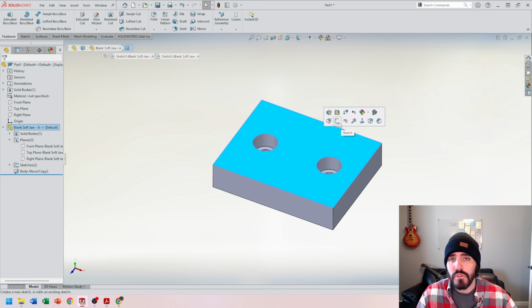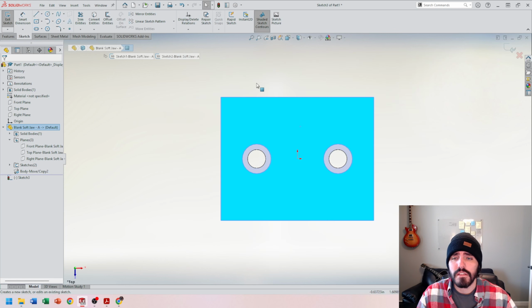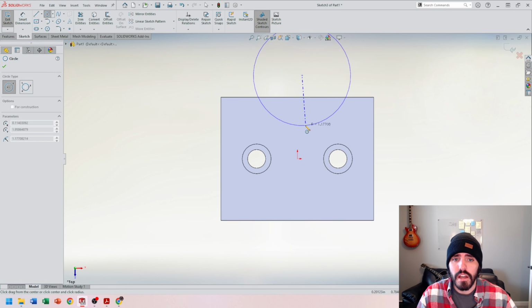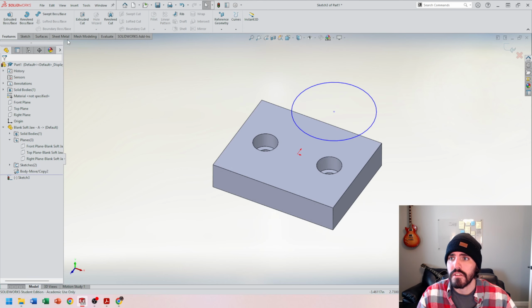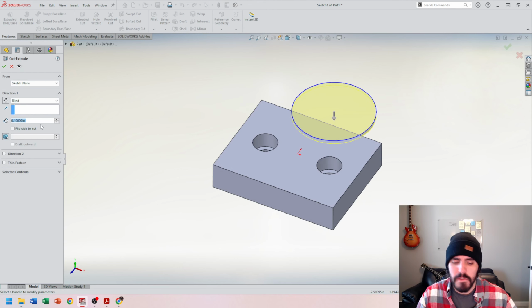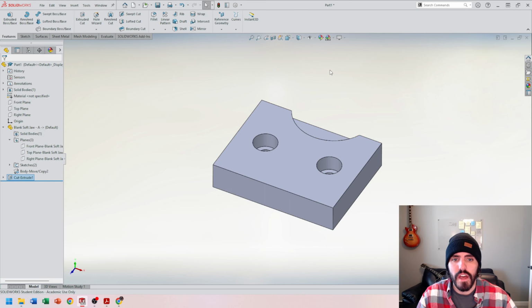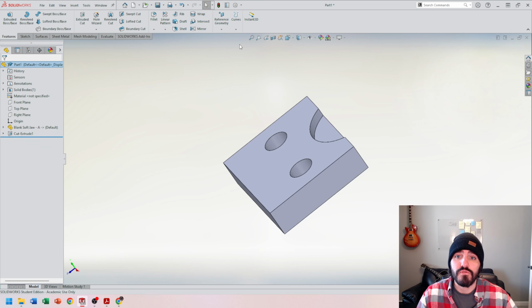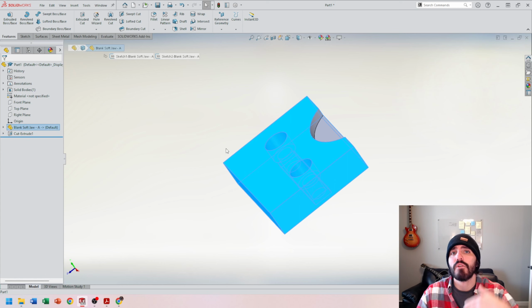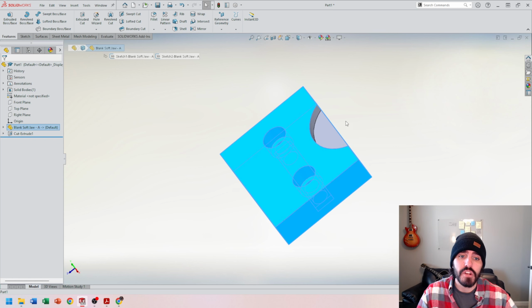But all I did with all those different soft jaws is I went in and applied geometry and then I did a cut. Or sorry, that's an extrusion. I'll do an extruded cut. I'll cut that down that distance. So that's all I was doing. All I was making was a new file and I was saving it out as my front or my back. And I was just inserting that blank soft jaw. And that's how it was updating, because it was treating it as its master or its parent file. This, in essence, is my child file.